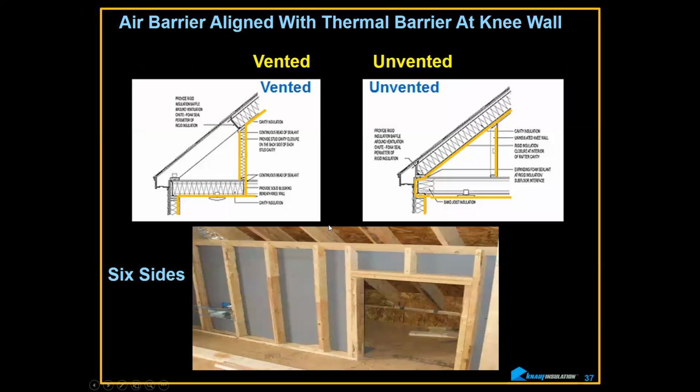Knee walls. So the thing about knee walls is that there are a lot of details in a knee wall to get them right. And one of them that's mostly overlooked, where this is actually an unconditioned space, where in here it's actually conditioned space. But because of this unconditioned space, you don't want airflow to get across. So again, 2 air barriers. Think about it, 2. They keep suggesting these 2 air barriers all the time, but there's no statement in the code that says you have to have them.